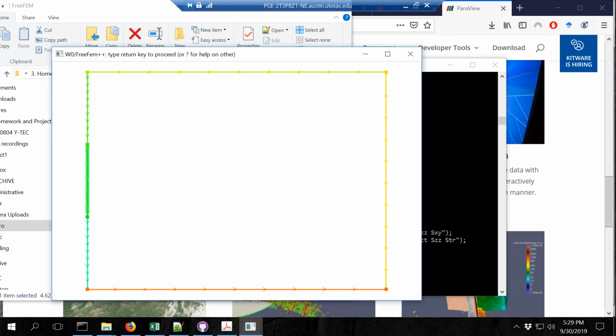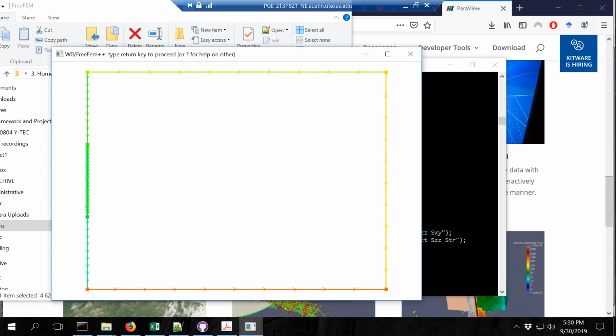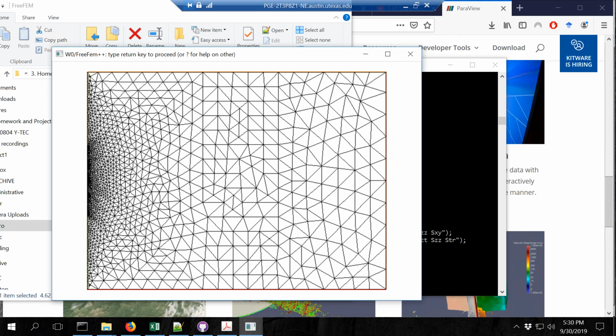And again, this is the domain, actually with closer dimensions to what you have to do. The fracture is there in the middle. These are the boundaries. I'm going to press enter. That's the mesh. Make sure that you don't want a lot of meshing in the far away boundary, but you want a very fine mesh close to your fracture. Also, you want a fine mesh at the tips of the fractures. Otherwise, you may get some errors in the solution.